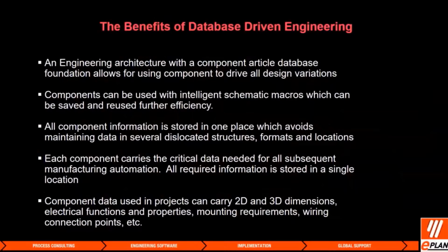And that is that we've got a component article database foundation underneath the software, which allows us to drive a lot of design variations once we have those components in our database. Components can be used together with intelligent schematic macros, which then can be saved and reused and drive further efficiency, so that we're creating large chunks of circuitry inside of the panel design and can save those and reuse them.